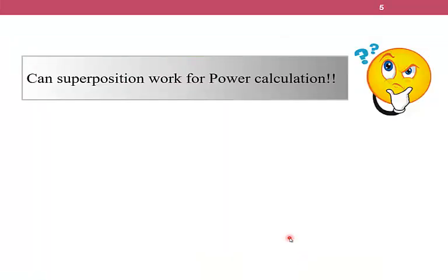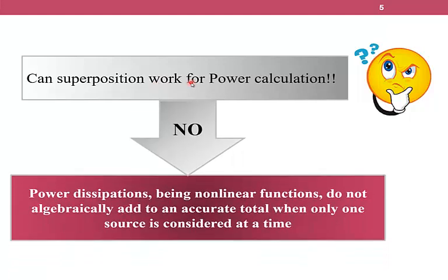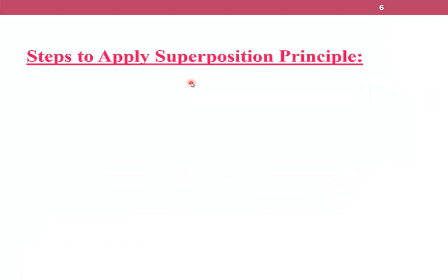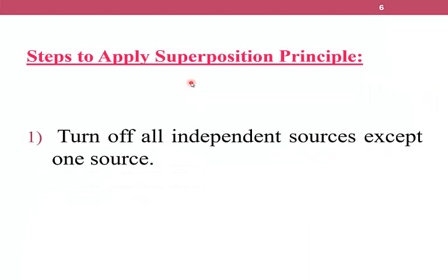So a question might come to your mind: can superposition work for power calculation? The answer is no. Power dissipation, being a nonlinear function, does not algebraically add to an accurate total when only one source is considered at a time. Steps to apply the superposition principle.